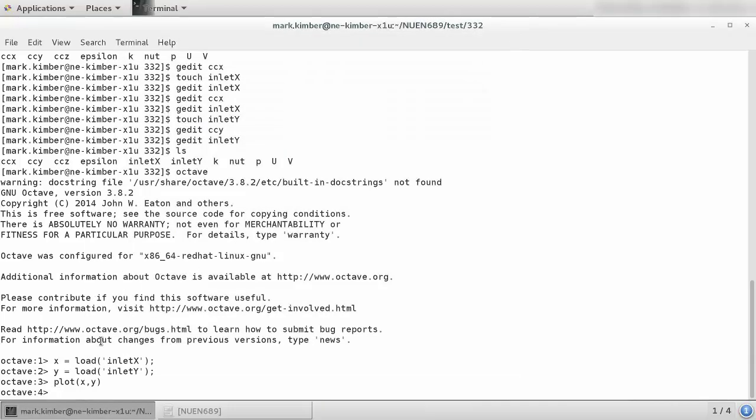So now I've got a vector x and a vector y in my Octave workspace, and now I just need to create a velocity vector in the z direction, and using my function, I can call this uz equals 1 minus x subtract 0.05 divided by 0.05.